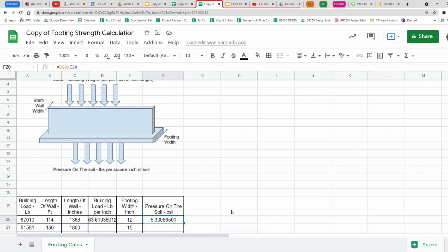So I've got a soil limit that my geotech gave me, and I'm going to just check my design. I've done my building design now, and I found out my load of the building and how much it's going to carry over, and I just calculate on through to figure out my soil. How hard is this going to push onto the soil? And if that number is smaller than what the soil can handle, I'm good.